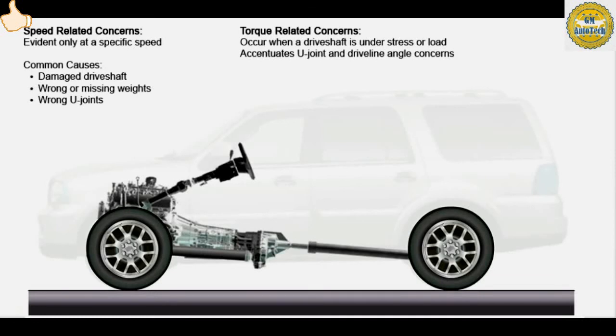The second type of concern is torque-related. Torque-related concerns occur at lower speeds, typically during acceleration after a stop. When the drive shaft is under more stress, components like worn U-joint bearings or incorrect driveline angles have a tendency to cause noise and vibration.